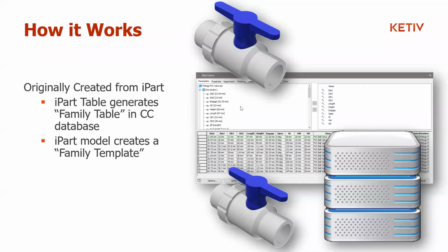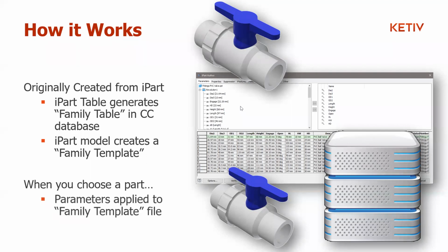What happens is when you actually choose a part in the content center, like I did a second ago, a nut, bolt, pipe, or O-ring, it takes the parameters in the table and quickly applies them to the family template file, does a sort of save as, and generates a new file in the content center folder or a custom folder.